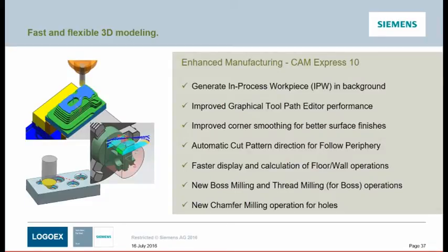The other leading manufacturing CAM solution for Solid Edge, CAM Express, has been improved in its latest 10 release. In-process workpieces can be generated in the background, allowing other projects to be worked on while it calculates. The graphical toolpath editor has been improved in relinking toolpaths that have had a portion cut away. Corner smoothing for Z-level and flow cut operations has been improved for better surface finishes.